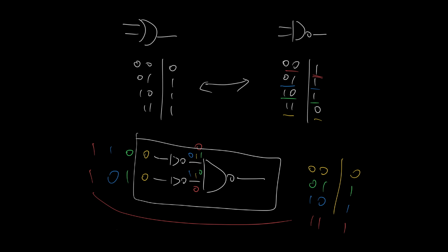So let's put everything together to check we remember everything. If I want to implement an exclusive OR gate using only NAND gates, I first write down its truth table. Then I can derive the sum of product form by looking at this row, then this row. The first row with a 1 says that the input needs to be a 0, so I put an inverter here and a 1, no inverter. That goes to an AND gate.